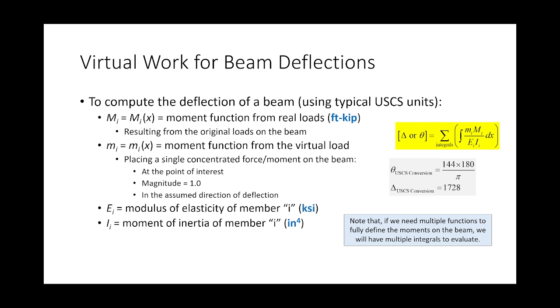Virtual work for beam deflections. Again, I'm not going to make you do shear deformations. I just wanted you to understand it. For beams, obviously what I'm most interested in, and really with frames too, is virtual work for flexural deformations. So we're summing the integrals of little m big M over EI to fully sum up the energy in the system.